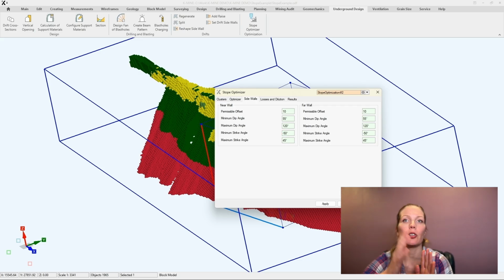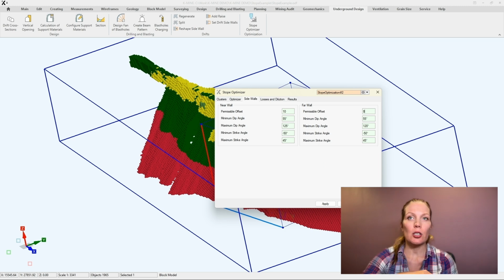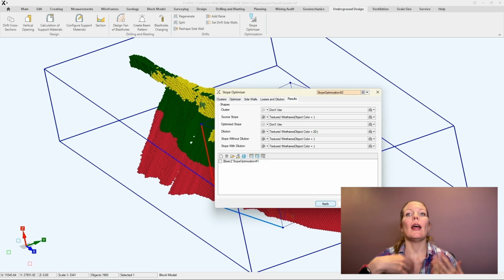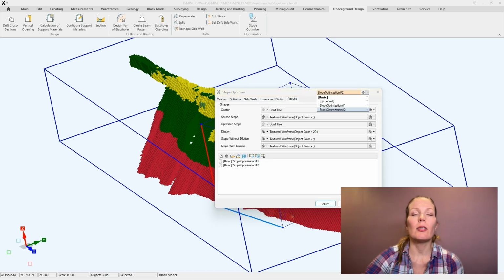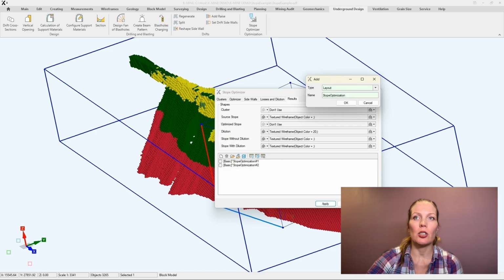So next come geotechnical constraints. Removing weak zones, limiting spans, enforcing sidewall stability, and if there is a section along depth with unfavorable fracturing, that section is simply marked as inadmissible and excluded even if grade is excellent. This is crucial in faulted underground gold mines where rock quality can change dramatically within a few meters.